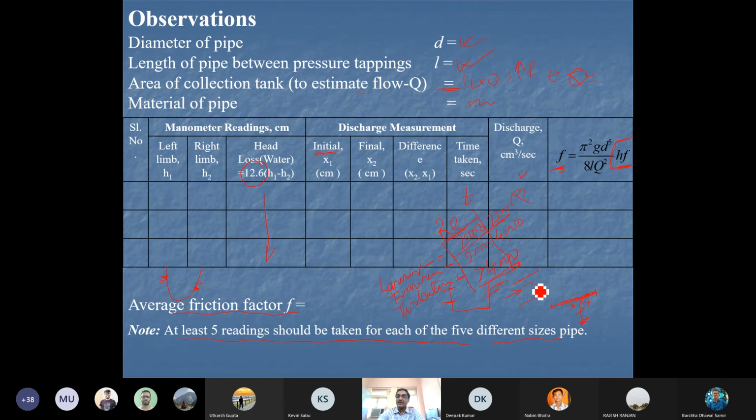So it is turbulent. Any clay particle of 0.0002 millimeter is not getting deposited, because it is in turbulent flow, so automatically it will go off. But sometimes the system is off. So any corrosion, meaning molecules attached to the surface of the pipe over time, will certainly change the friction factor or frictional value of this pipe material. And if it is changing more than a certain limit, we need to change the pipe to avoid any energy loss in supplying the water or any liquid in that pipeline system.